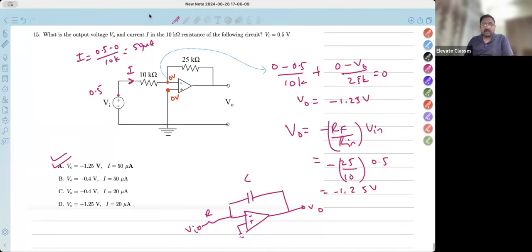And then comparators. We have also solved comparators. Op-amp without feedback or op-amp in saturation behaves as a comparator. Then we also solved op-amps plus diode questions, if you remember. We have that in our notebook. And finally, high pass filters, low pass filters. Remember high pass and low pass as well. Low pass filters behave as integrators. High pass filters will behave as differentiators. And especially remember the transfer function for both. We have derived the transfer function for low pass filter and for high pass filter.